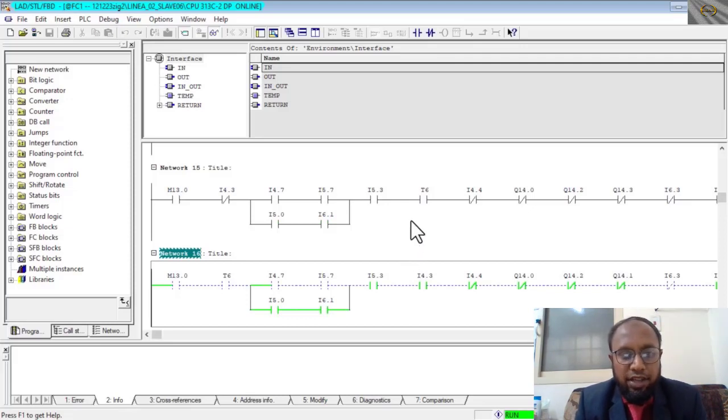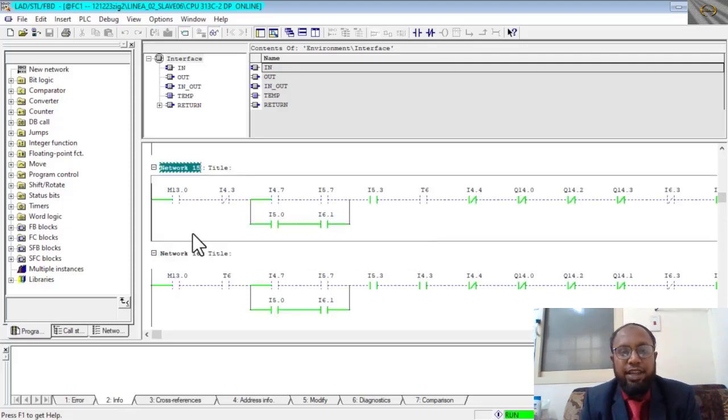Here we found I4.3, which was a limit switch. That limit switch is not used in our case. In our operation we do not use it, but it is always coming in the on condition. It should be normally open, but the limit switch is stuck. It gives the signal, and the PLC gets the triggering signal. For this reason the condition doesn't run.